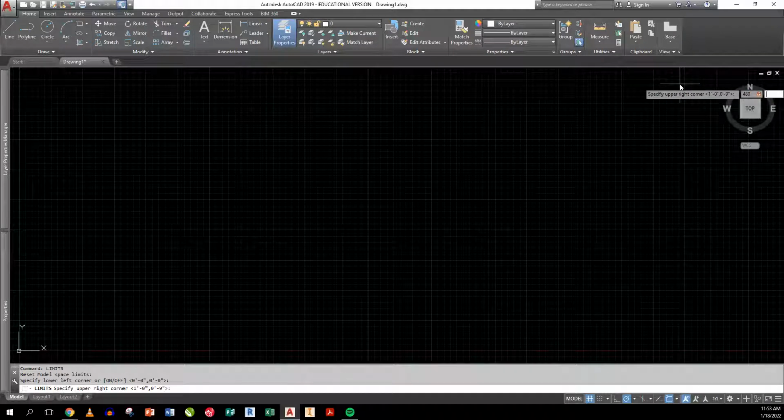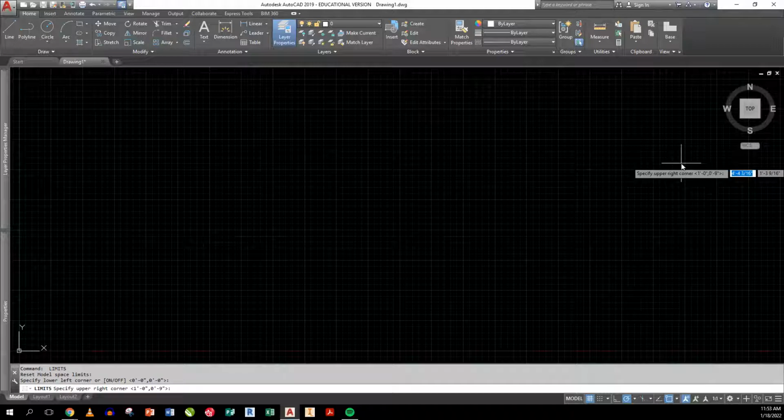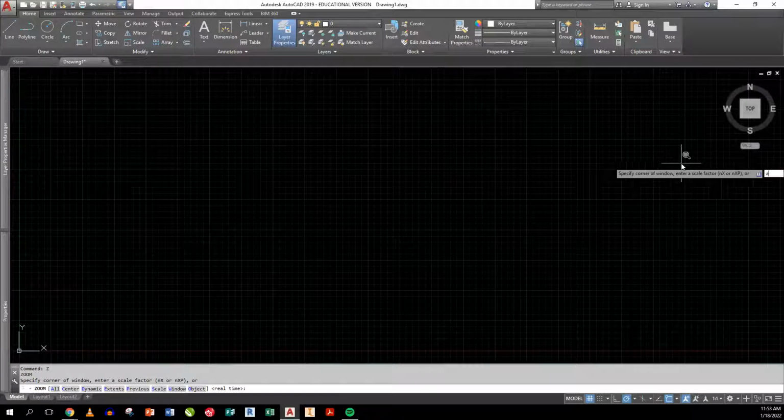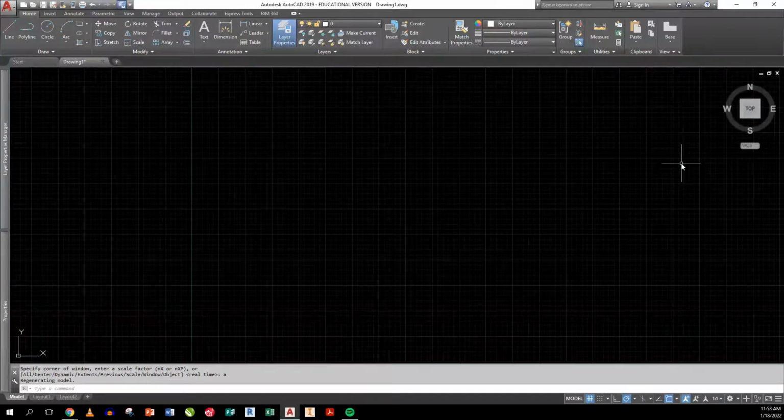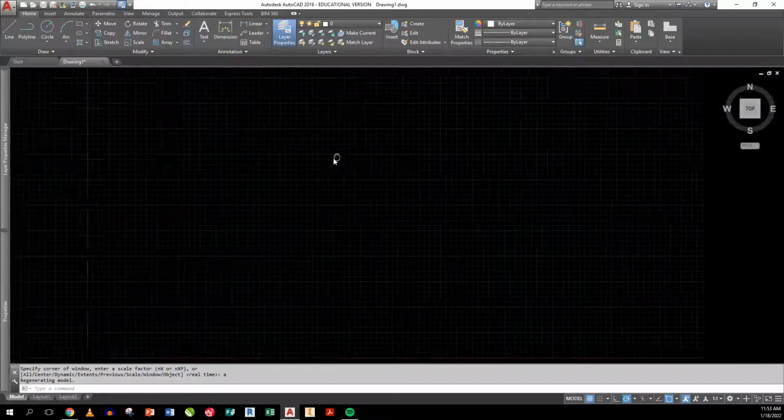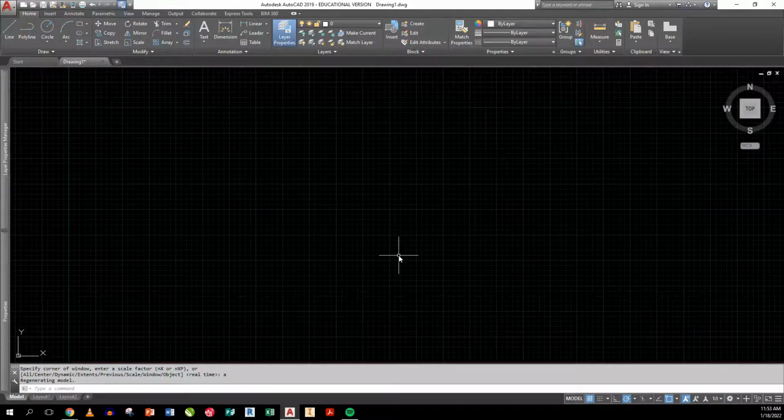Actually, let's go back here a little bit. I'm going to go back in and start this over. So what I'm going to do is set this to 400 feet. I missed the apostrophe, comma, 300 feet. And then I'm going to do zoom all, Z-A, Z-enter, A-enter. And what I've done is I've set my units up. I've got plenty of room to draw now.